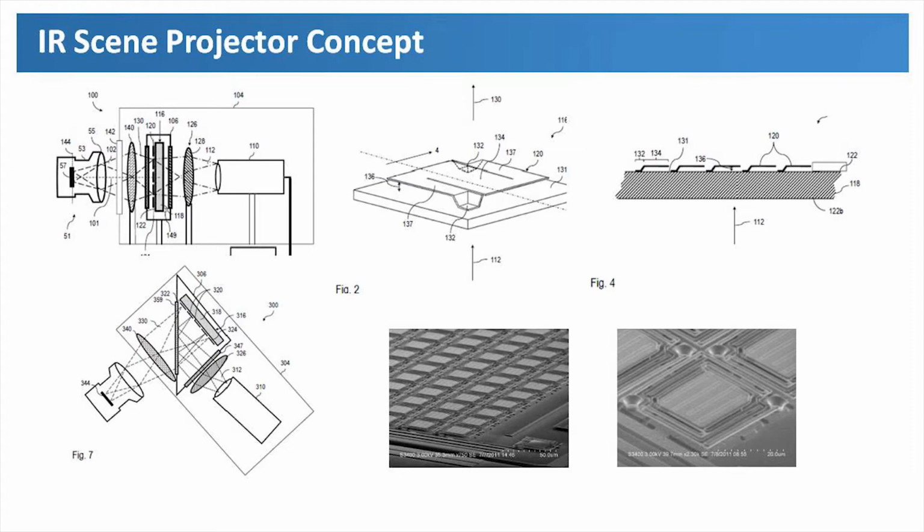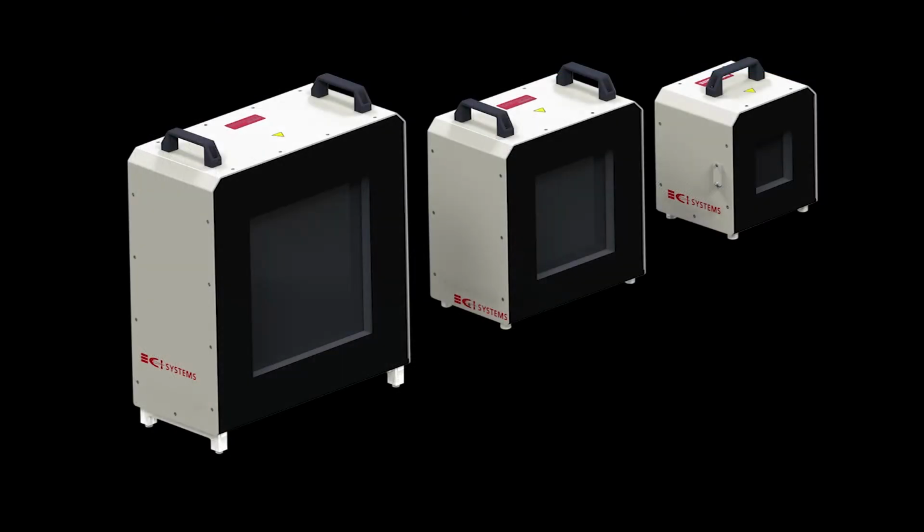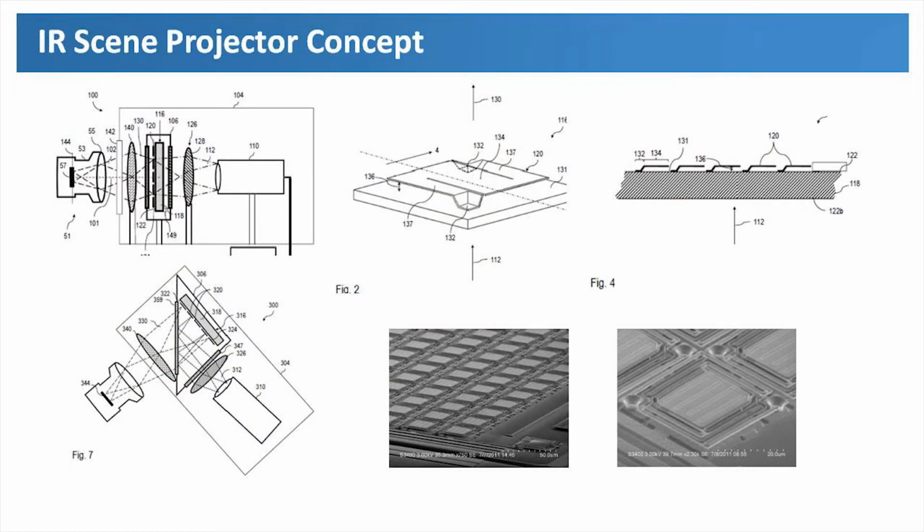Now, in each of the pixels, the absorption of the visible radiation causes an increase in temperature. So basically, the temperature of each pixel increases, and the pixel starts to radiate infrared radiation. Each of the individual pixels works like a black body with a Lambertian distribution of radiation. So generally, when the temperature of each pixel increases, its emission curve is exactly the same as a black body, which means it's a Planck curve. And you see that the peak of emission changes depending on its temperature, exactly like the black body would behave.